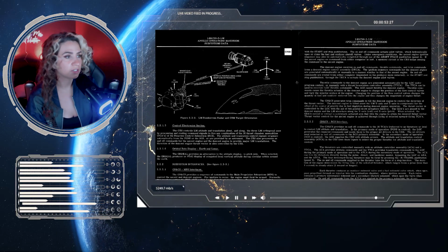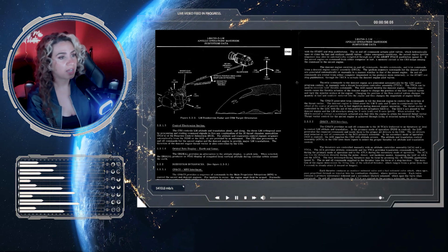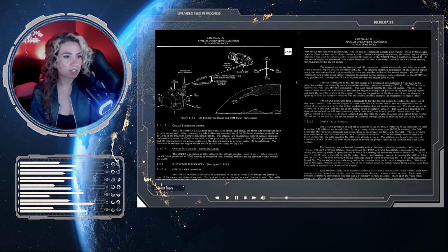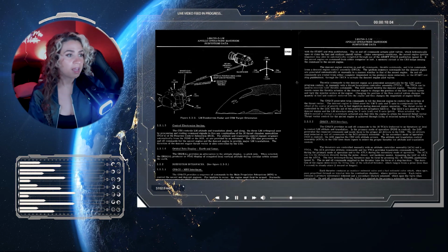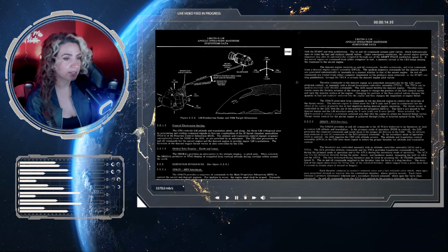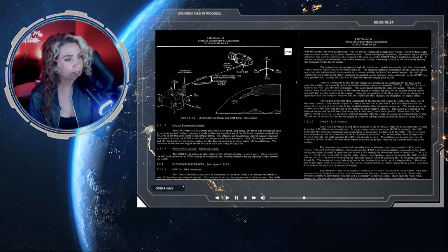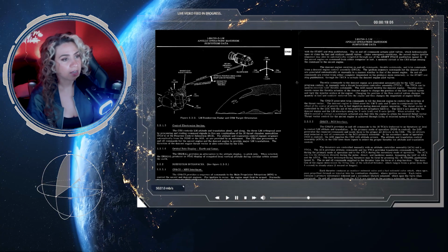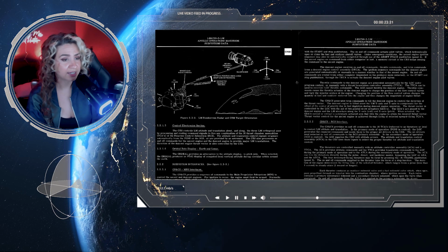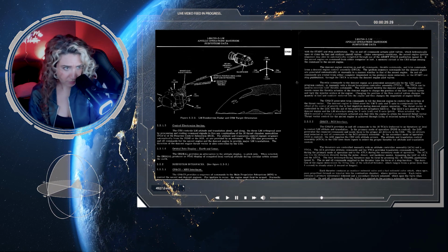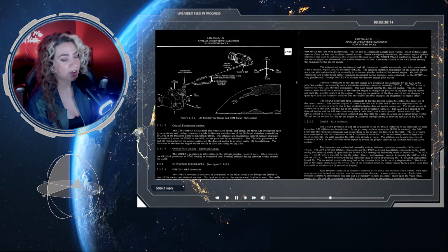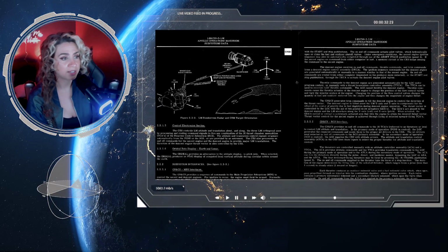The thrust vector is controlled by the LGC with the aid of the two gimbal drive actuators, GDAs. The GDAs are pinned to the descent engine and the LM structure along the y-axis roll and the z-axis pitch. When actuated, the GDAs extend or retract a screw jack actuated arm that tilts the engine to attain the desired thrust vector. Thrust vector control of the ascent engine is achieved through firing selected upward firing TCAs.